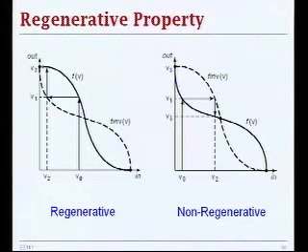And in order to analyze that, we basically plot the voltage transfer characteristic of a gate that's described here with this function f of v, and this is a solid line in this graph. And you also model the next stage with its inverse transfer function, because for the gate in stage I, you have output versus input relationship, but for the gate in stage I plus 1, you have input versus output.